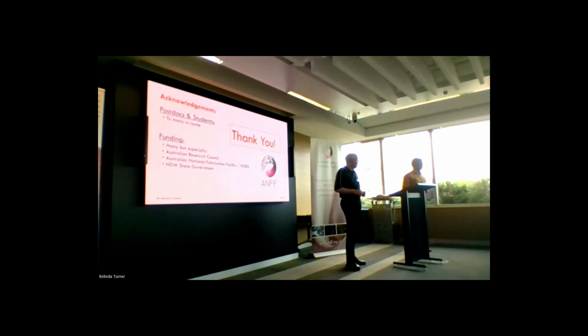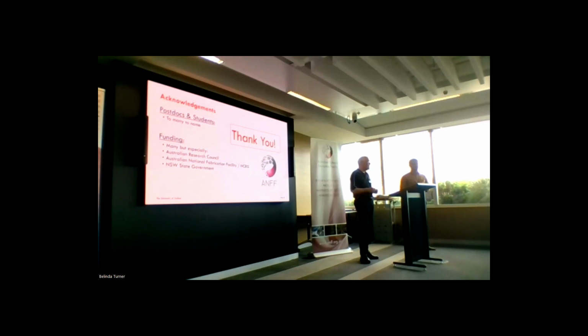So is it easier to bend them into very small radiuses of curvature then? Well, I can tie a knot in this, but silica fibre, when you've got it coated, you can take it down to about 1 millimetre bend radius. Silica is actually quite strong. It's just surface imperfections will cause it to break. But yes, we can take them down quite small. There are some tricks because the guidance we're using for these polyurethane fibres is capillary guidance, and that isn't very good at small radiuses.